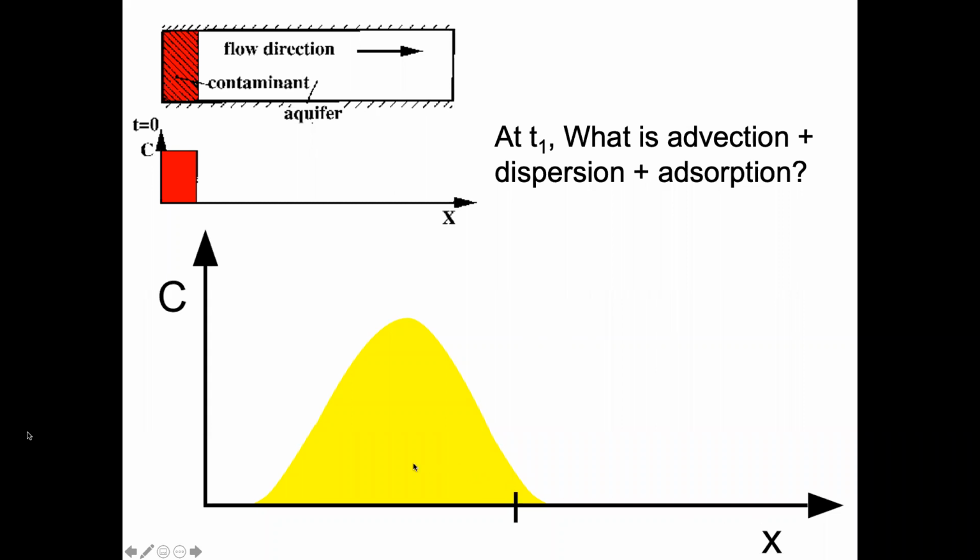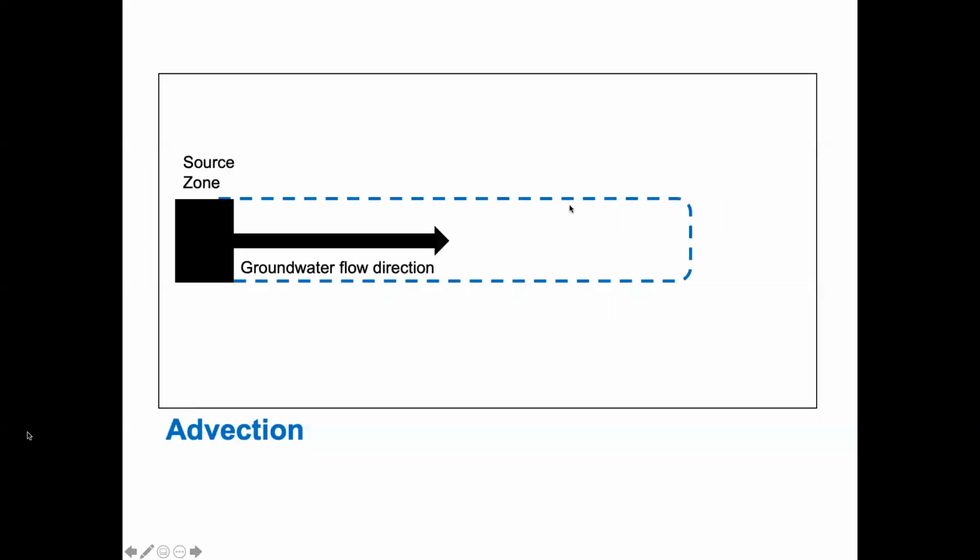And the reason for that not making it as far is you can think of all of these grains, right, that our surface area that's in the subsurface, and a certain proportion of the chemical is being picked up, and then it's finally being knocked back off. And so you again get this kind of slowing of the effect that would normally take place if you have an advection and a dispersion.